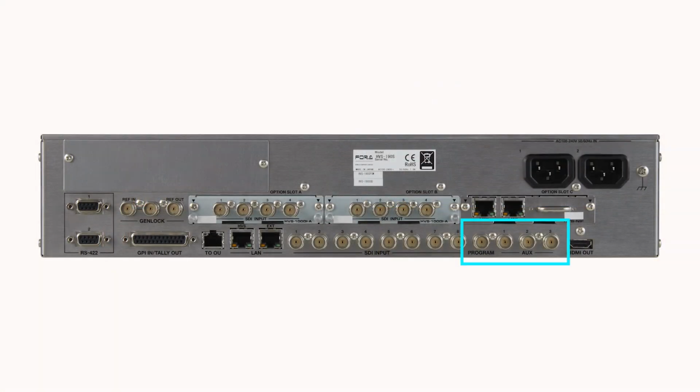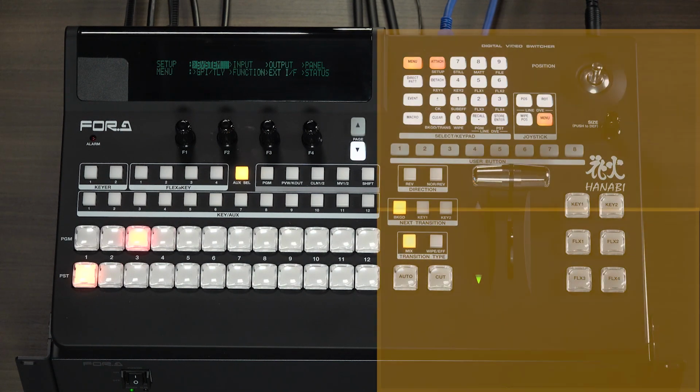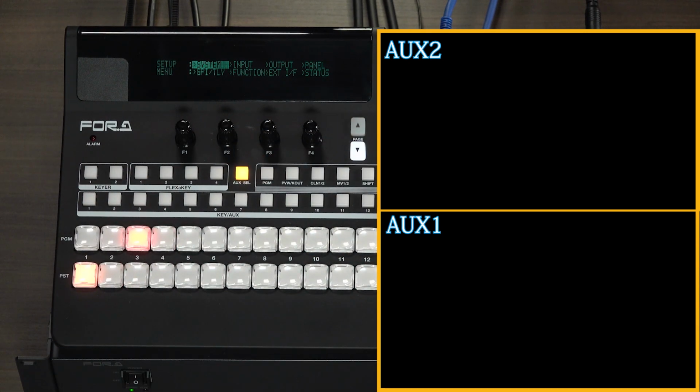HVS-190 has 4 SDI outputs as standard, including 1 PGM output, 3 auxiliary outputs, and 1 HDMI output. Select the auxiliary output video. First, select from the OU buttons. Assign Preview to Auxiliary 1. Press Auxiliary 1 while holding down the Auxiliary Select button.